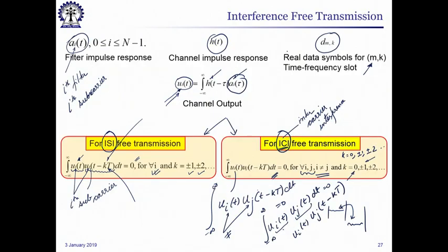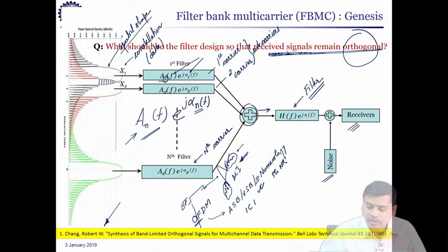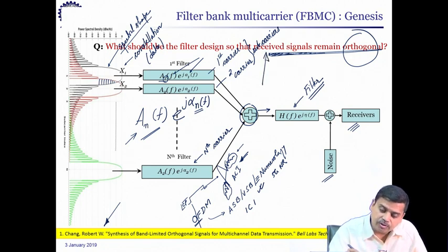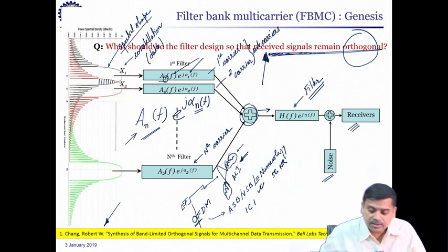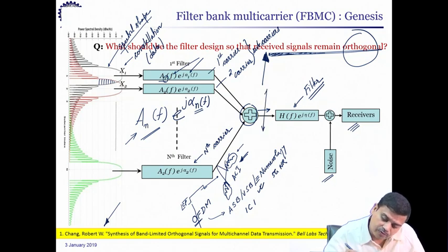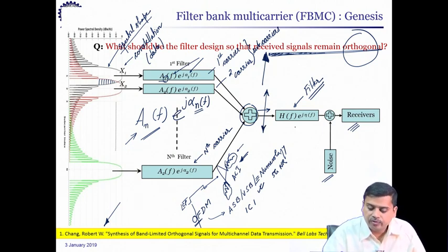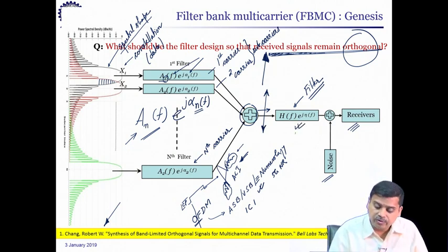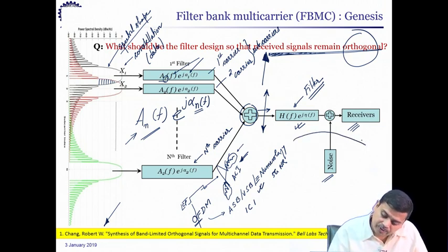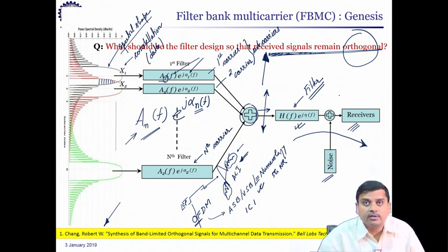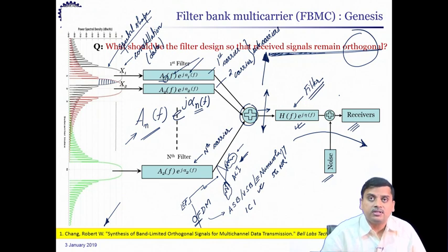Okay. So, if we go back and look at this whole setup, we want the received signals to be orthogonal. This is a criterion one has to pay attention to, whereas we are not restricting ourselves to the orthogonality criteria over here. If we had restricted ourselves to that, we would not have taken the channel into account, and we could not have commented on what would happen when the signal goes through such a channel. So, this is more generic: given a particular channel, can you design the signals such that they are orthogonal at the receiver end.